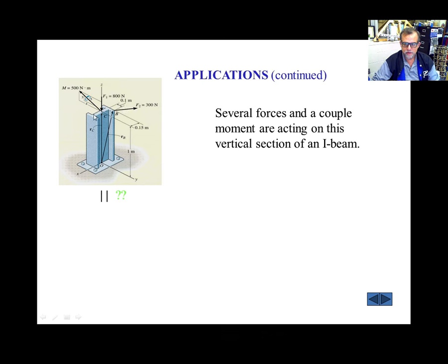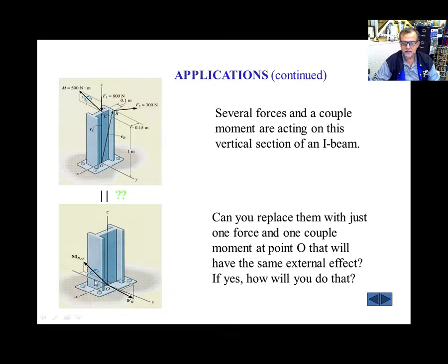However, if I convert that to an equivalent system at the base, now it's a little bit easier to say how would be the behavior of this element if I just converted it to one force and one moment. Now I can say, this reaction here is going to counter this force that is trying to pull it in this direction, and at the same time these bolts are going to produce a moment that is going to counter the effect of the moment that is generated there. So basically what you do for converting that is for simplification and to make it easier to visualize what is happening there.